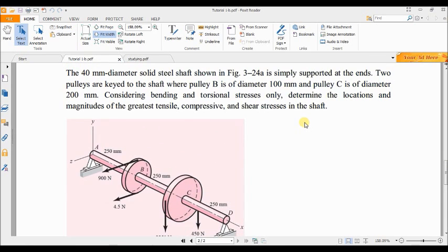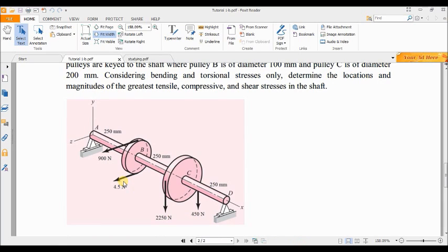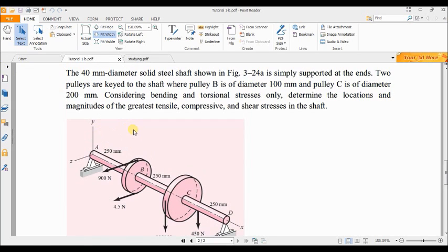To do this task, first we need to make a load analysis on the shaft to find the location of maximum moment on this shaft. As you can see, this shaft is supported at location A and D. For example, there are two bearings at this location. That shaft is able to rotate around its axis X.